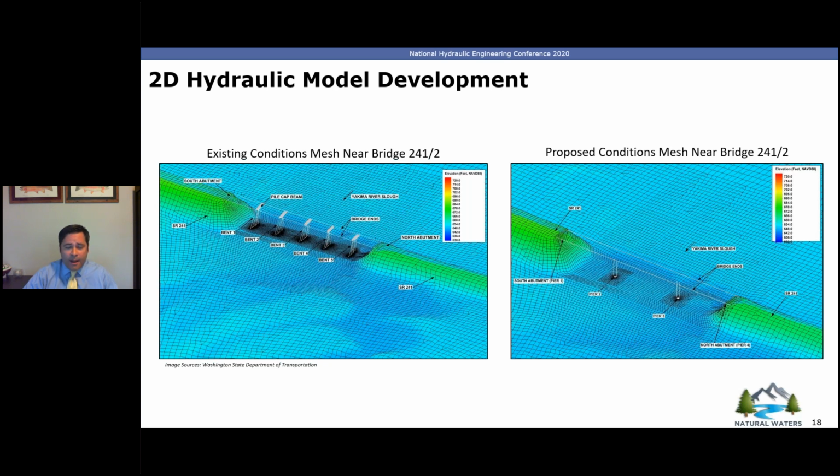With that said, I would say that an important takeaway is, whether you're using patching or paving, just make sure that you have a good number of elements that represent the waterway opening. There's been some misconception with various models on how that is performed. So I will just use that opportunity to say make sure that you have a large number of elements that represent the channel cross section, independent of what model platform you're using.